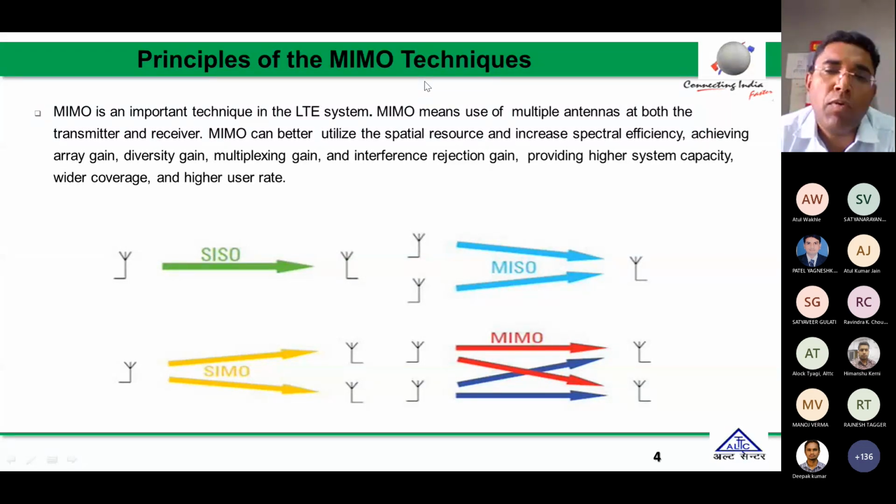That is known as the resource block in 4G as well as 5G, where users transmit their data in frequency and time domain. All are having different frequency and time domain resources. That's why the intra-cell interference is theoretically nil, meaning zero. That's why it is more suitable to transmit higher order MIMO in the case of 4G and 5G.